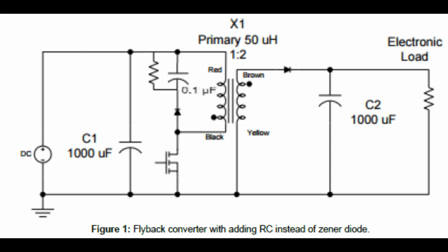The famous supplier for this type of IC is Power Integrations. They give everything as a single IC, including the MOSFET and all control circuitry. Mostly you may have to add one more optocoupler and then the transformer and a few external components, and then the circuit will be ready. Power Integrations gives complete design details for each and every component so that one can follow the guidance and make this type of power supply easily.